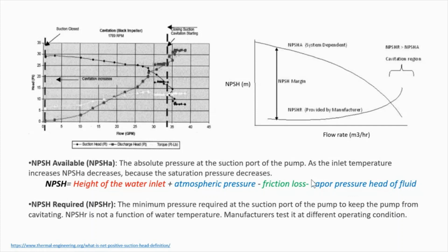As I told you, the temperature is supposed to be constant throughout the process, but if you have a high temperature in your fluid, then your fluid can vaporize at a much lower pressure, right? So you have way more bubbles in a hot fluid than a cold fluid. So this is where that pressure needs to be accounted for and calculated as well.